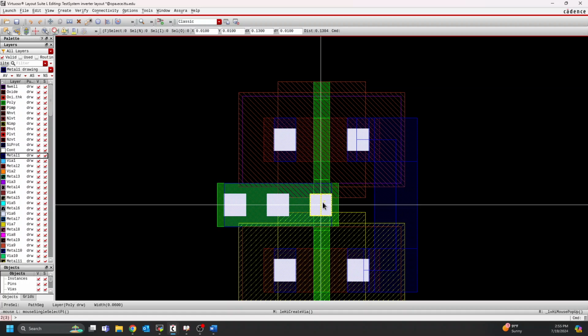This isn't something that you necessarily want to only rely on in the beginning. That's definitely something that you can use throughout the entire process, but it's good to start checking your design rules earlier rather than later. Because if you design something more complex, like maybe a D flip-flop, and find out that a lot of your rules are violated, you may have to completely relay everything out. And that can be kind of a pain. So it's much more useful to check and make sure you're following the rules earlier.